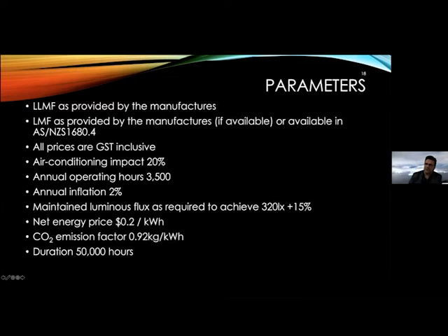We could talk about corridors, we could talk about lobbies, meeting rooms, but let's focus on offices. And offices are designed for 320 lux maintained, and I allow 15% of margin because it's very difficult to get exactly 320 lux.